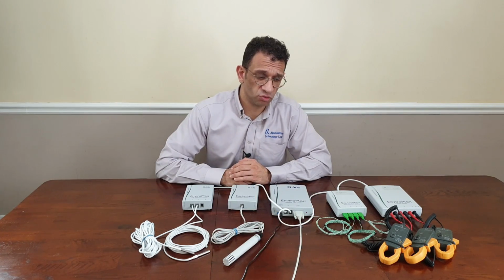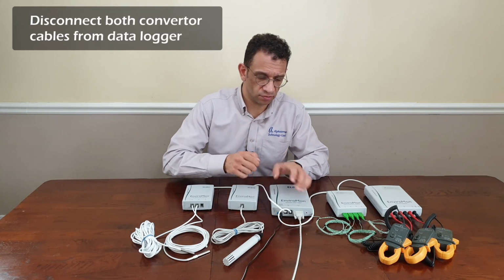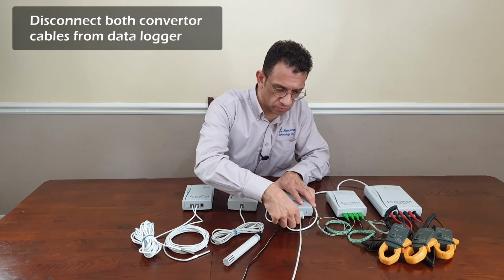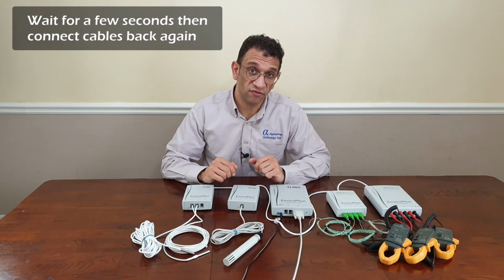So in this particular case, we're using both network ports to connect the converters to the data logger. So the first thing we'll do is we'll disconnect both converter cables from the data logger. We'll then wait for a few seconds, and then we'll connect the converter cables back.